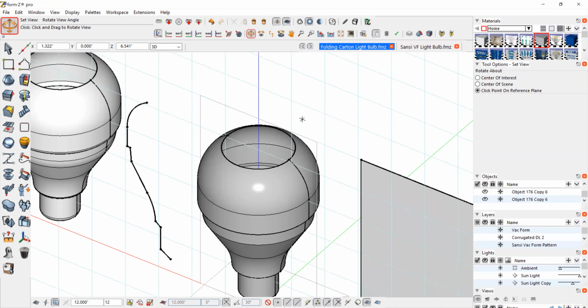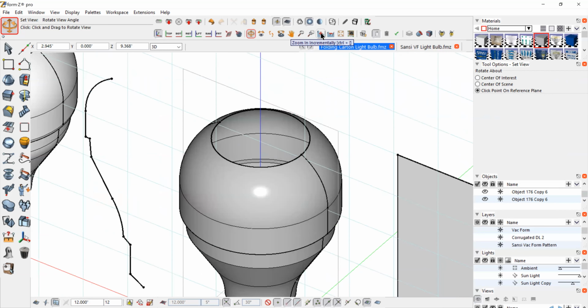If I want to make this a solid, this is a big distinction that we're going to have to talk about all the time. When you do surface modeling and solid modeling, those are two different types of entities. These are surfaces right here, and I can do certain things with them. But quite often, I'll need that to be a solid, which means everything has to be closed. Right now, I cannot make that a solid because it's only two surfaces.